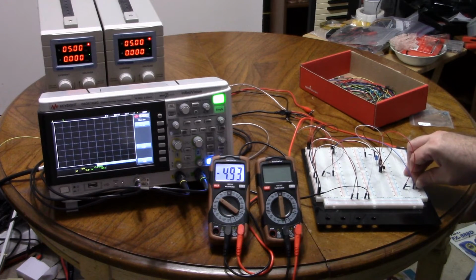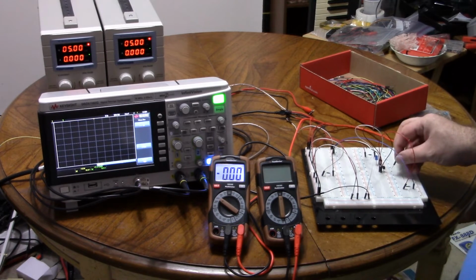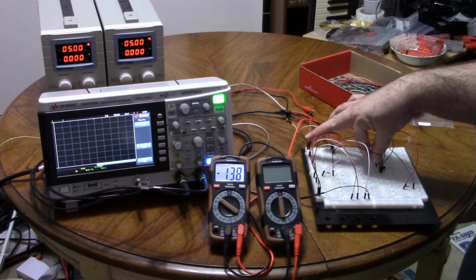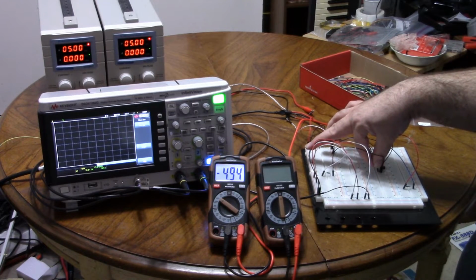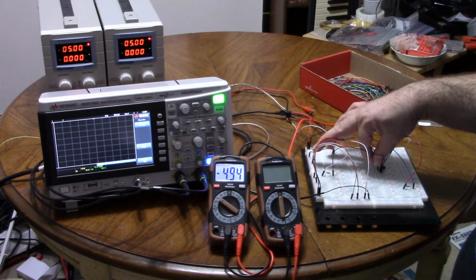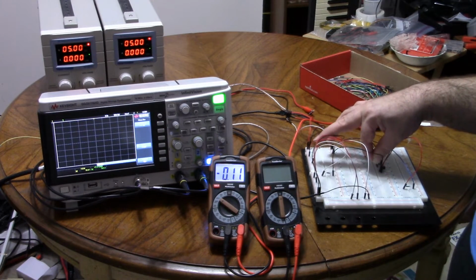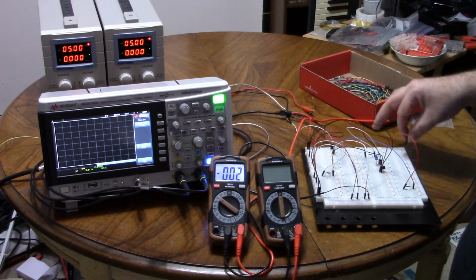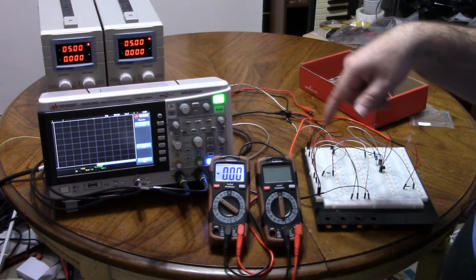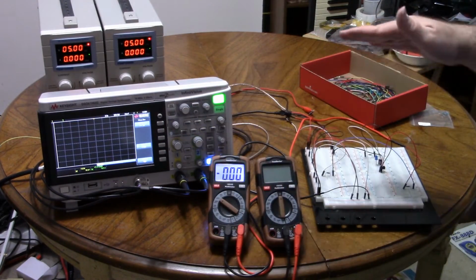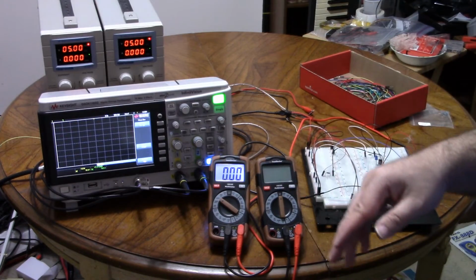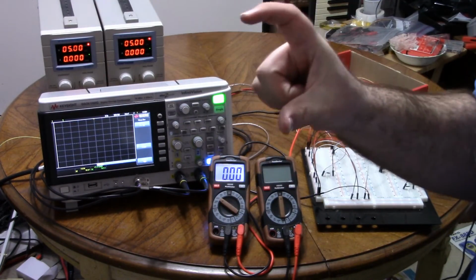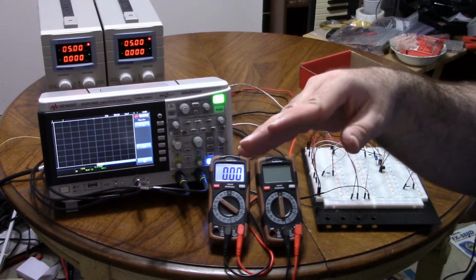If I measure the voltage, once again, at the output of the emitter resistor, we're at the minus 5. If I measure the emitter, it is at almost minus 5. We've driven down the emitter. The base, see, there's the emitter, minus 4.94, and the base is at minus 4.46. So it pretty much doesn't have quite enough voltage to be forward biased. But we had to go all the way down there and push the base down towards the negative end. So a normal signal that's not got that much amplitude is going to be passed just fine.